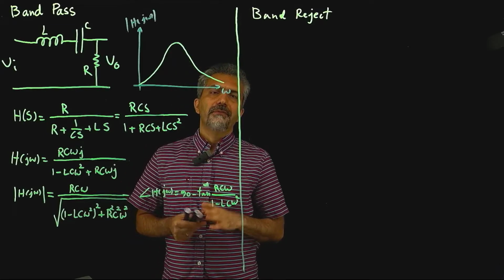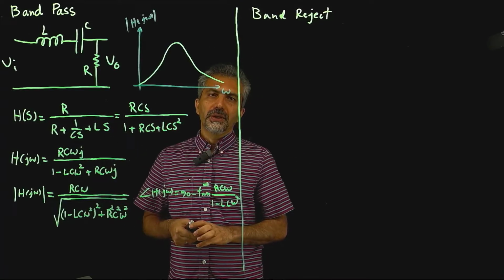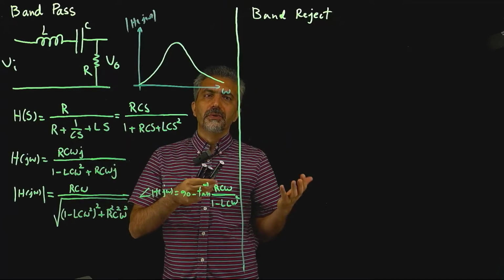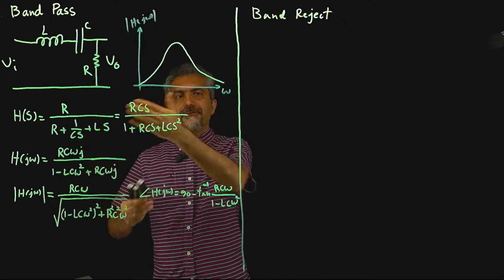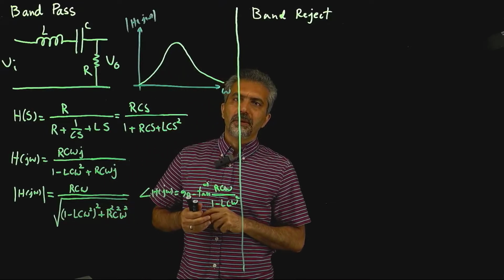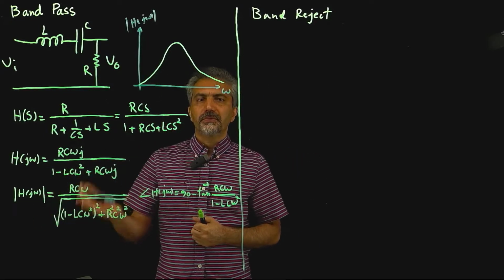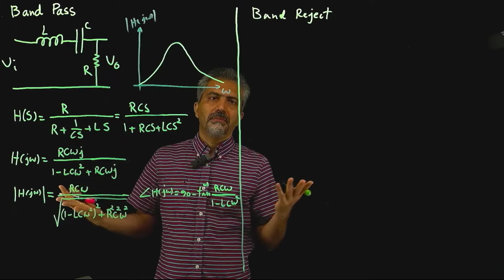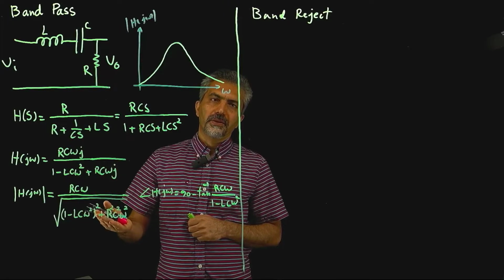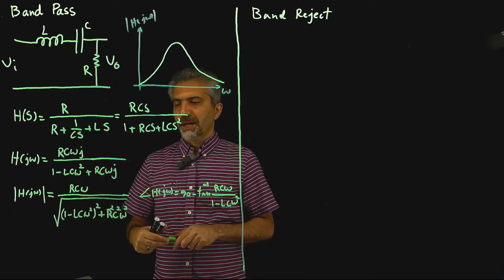Basically, we want to have a metric for what frequencies, generally speaking, are passing through the filter, which we're going to define as frequencies whose power is going to pass more than half through the circuit, right? So for that, I'm first going to have to find out what the maximum of H(jω) is. Generally speaking, whenever you want to maximize a function, you take the derivative, equate that to 0, find out what frequency is going to maximize or minimize the function, and then evaluate the function at that point, and you get the maximum.